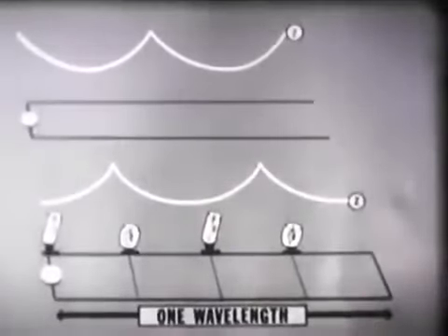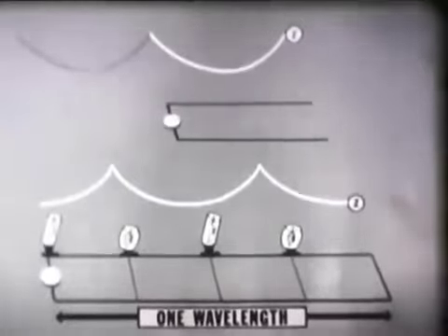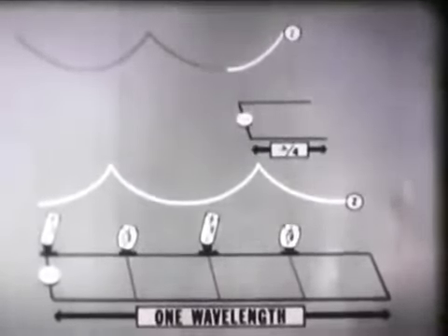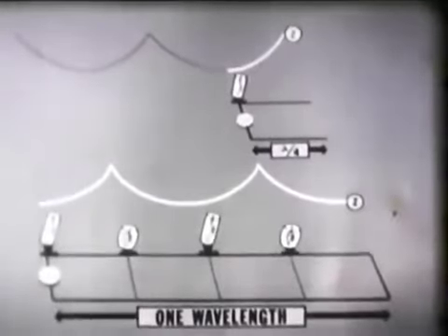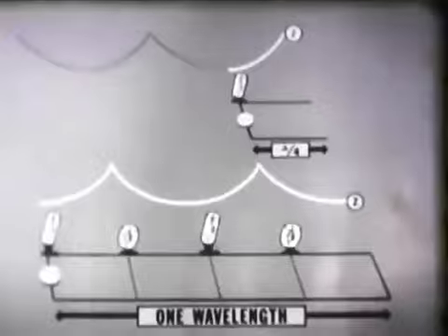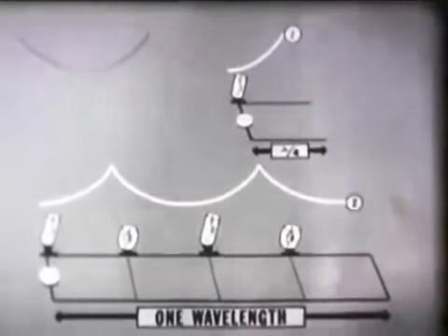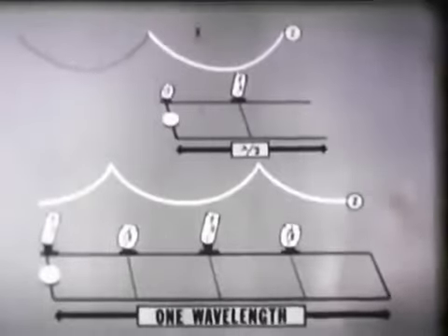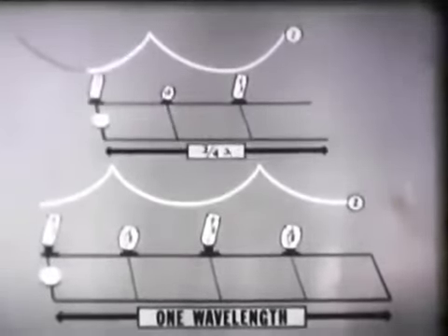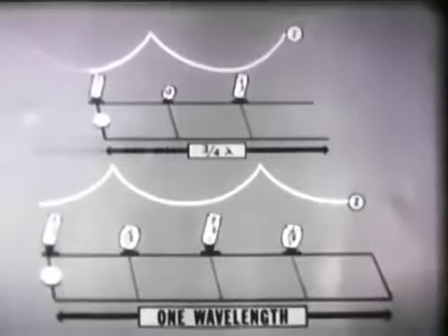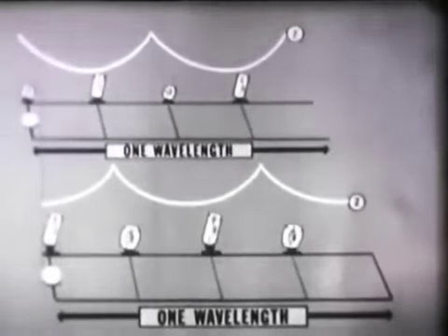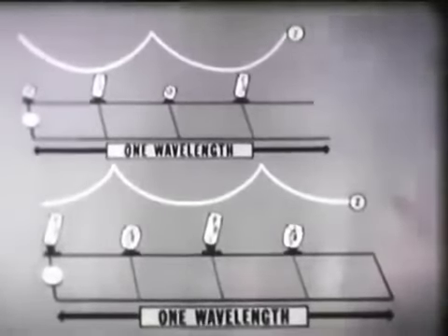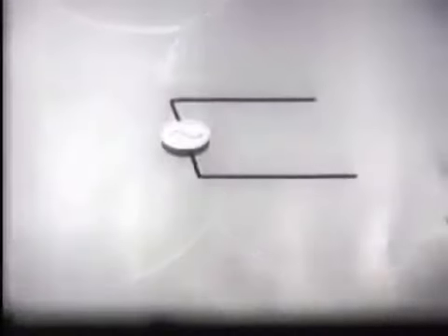The behavior of our open line can be investigated in the same manner. At the 1/4 wavelength point, the generator sees a condition of minimum impedance. This circuit can then be considered a series resonant circuit. Each time a 1/4 wavelength is added to the circuit, the condition changes. Thus, open and closed-end lines can be used as parallel or series resonant circuits, according to the length of line used. Because of this facility, they are known as resonant lines or tuned lines. In this quarter wavelength of open transmission line, we have the requirements for a radio antenna.